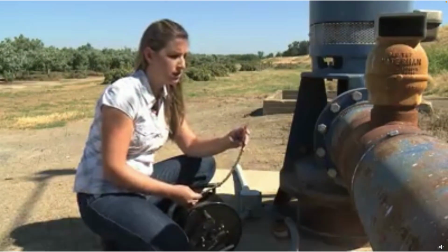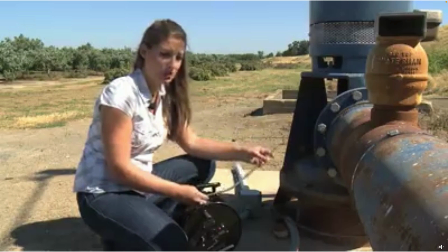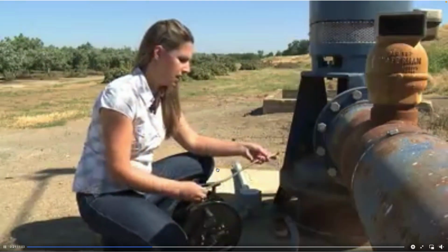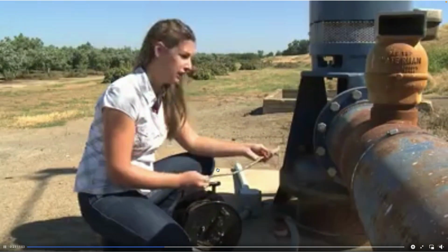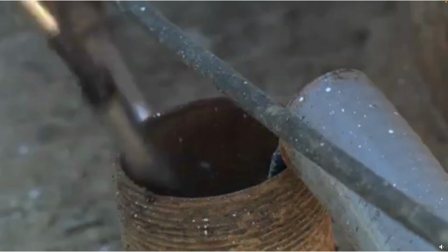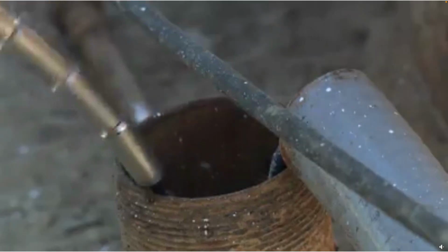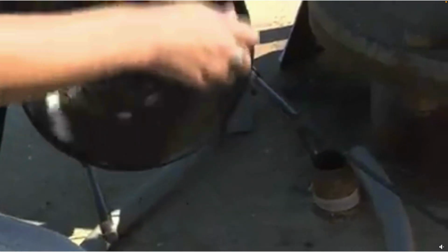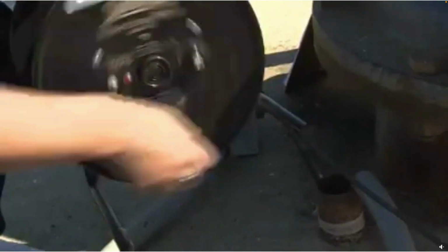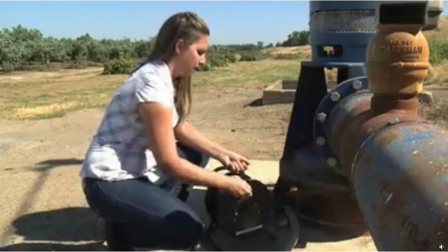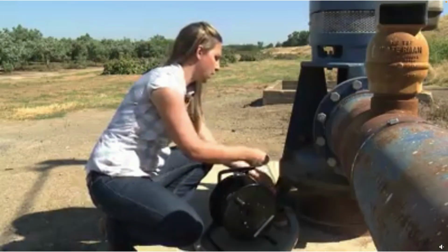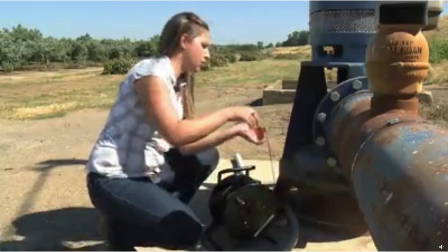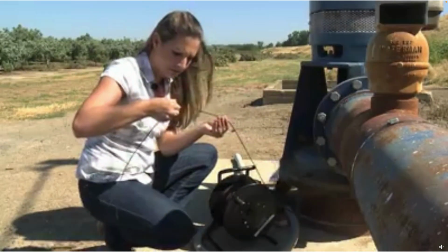All right. So, just for boreholes that are filled with water, you drill a hole. You can drop something down until you hit water, and typically what you drop down would be this probe, and all it is is two conductor wires with a weight on it. The conductor wires are present within that weight, and then when the conductors hit a water surface, they make a circuit and a light comes on at the surface. And then you record it in your phone or whatever data you have.